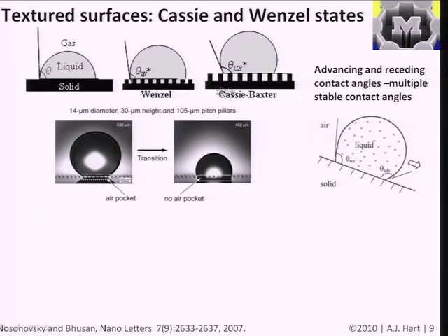basically how the liquid interacts with all the surface structures that you have. And there are two states, and the state where the liquid is penetrating, you could say, down to the subsurface here and basically wetting all of the surface area available is what's called the Wenzel state. And when the liquid is sitting up above the texture, it's what's called the Cassie or Cassie-Baxter state. And you can go in and look up, there are ways you can derive the contact angles in both of these cases depending on the roughness and surface energy. But basically what happens is if you manipulate this texture in response to the surface energies of the materials that the surfaces are made of, you can control the contact angle between the two.